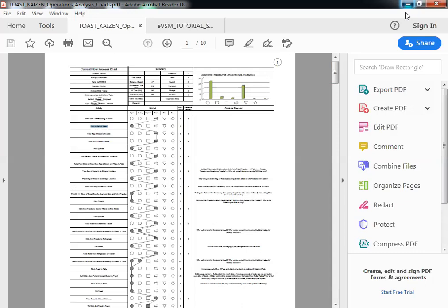So that, you know, if you were drawing this in a value stream map format, what you would do is you would eliminate all the waiting and other steps, and you would only look at the operation steps. And the operation steps would become the skeleton for your value stream map. And the transportation steps would connect those operations. In a value stream map, I can easily put a decision block and split the value stream. I think the value stream map is effective because it captures the information flows that the flow process chart does not capture.